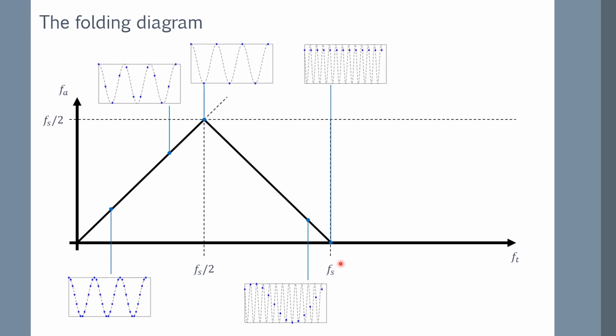If we match exactly the sampling frequency, this is the case where the droplets stand still. You can see that for the sine wave, we take a sample every exactly one cycle, which means that we get a sample and then we miss everything inside the cycle, and then we get another sample exactly where the previous sample was. Every sample looks exactly in the same place, and it doesn't look like it's doing anything. So this is the example where the droplets look like they're standing still.